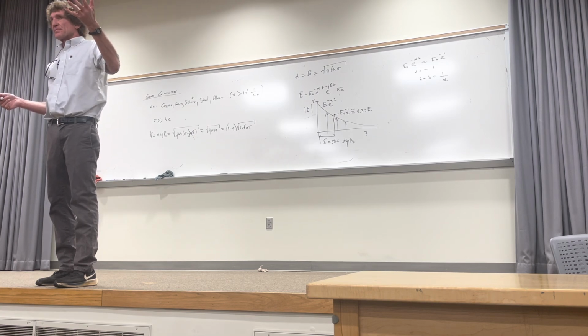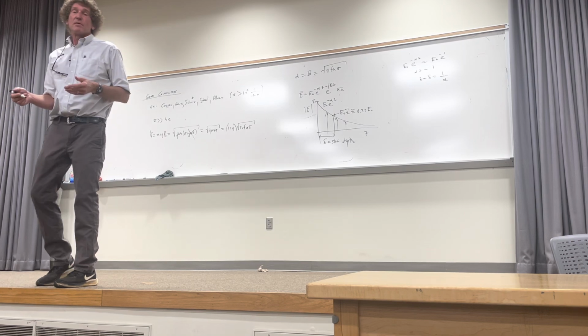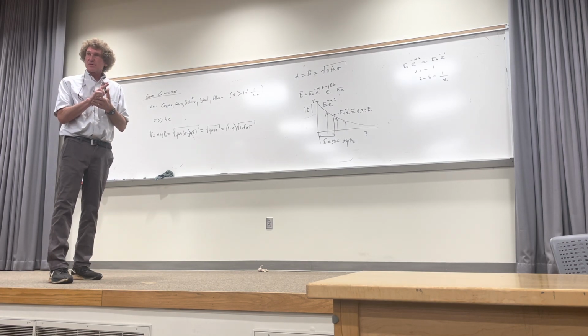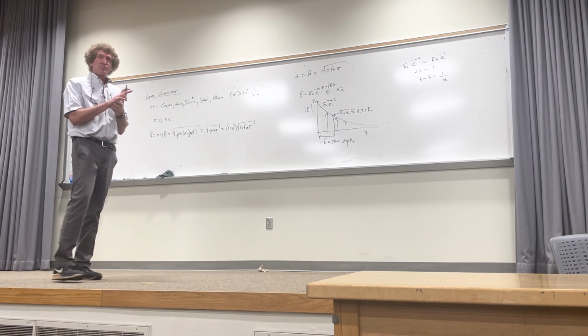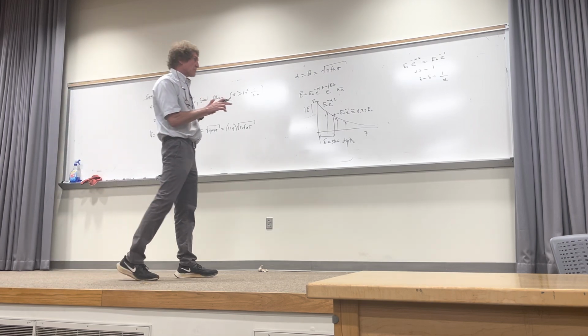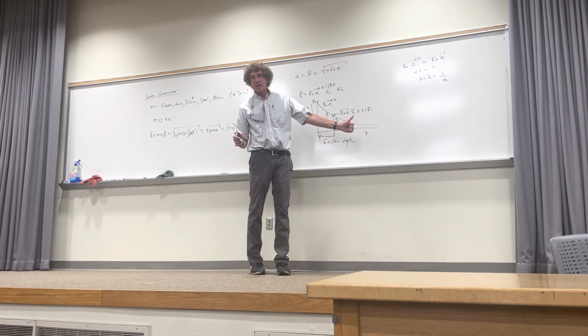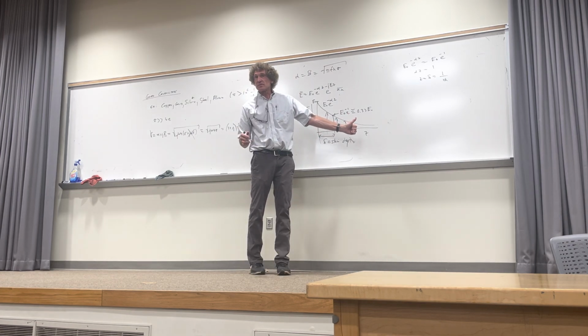This is called the skin depth, and it should make relative sense to you. It's a metric for how fast something attenuates, or how much distance the wave can be expected to move through before it's significantly attenuated in any material. Now, some of you probably remember rules of thumb: if you're 5 skin depths in, you basically have a signal that's gone.